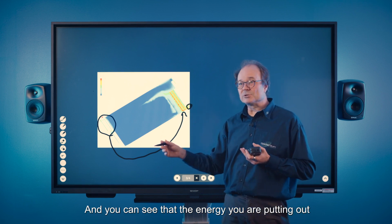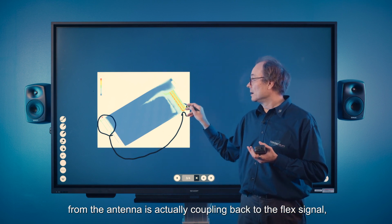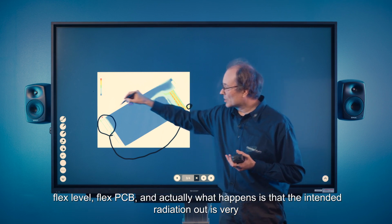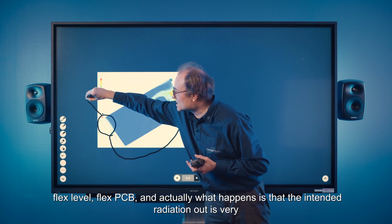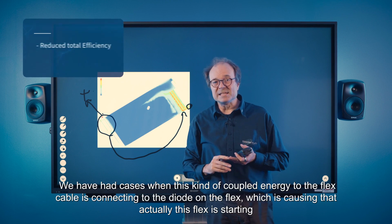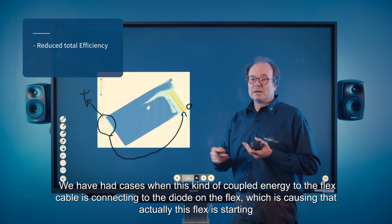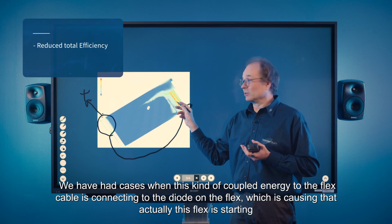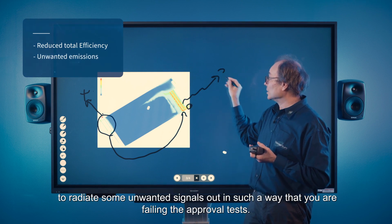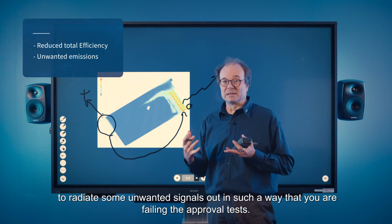The energy you are putting out from the antenna is coupling back to the flex PCB, and what happens is that the intended radiation out is very much reduced. We have had cases where this kind of coupled energy on the flex cable connects to a diode on the flex, which causes the flex to radiate unwanted signals out at such a level that you fail the approval tests.